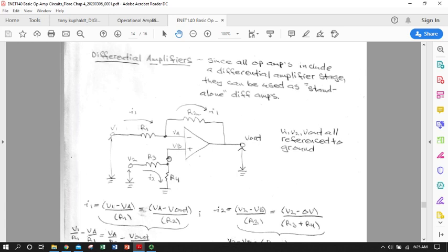So we kind of have something that looks a lot like a voltage divider, looks like a feedback network here in both cases, but it is only R2 up here that is actually accomplishing the feedback because it's the only one that is connecting the output voltage back into the inverting terminal. So R2 is our feedback resistor, R1 is serving as our inverting terminal input resistor, and these are just adjusting our voltage going into our non-inverting terminal. So now we have two voltages input coming from ground. They could be AC or DC, but we're going to reference them both to ground.